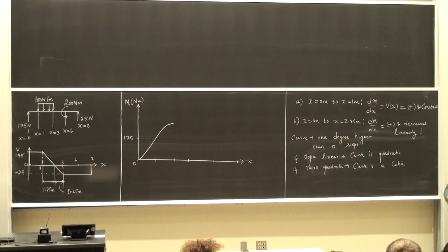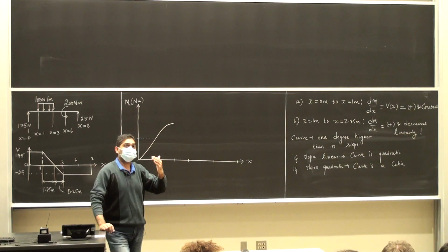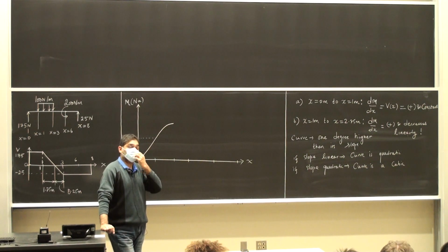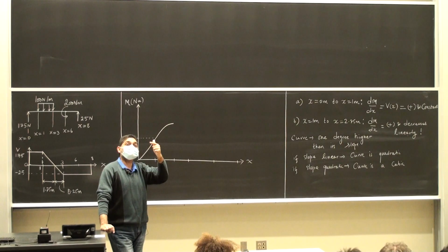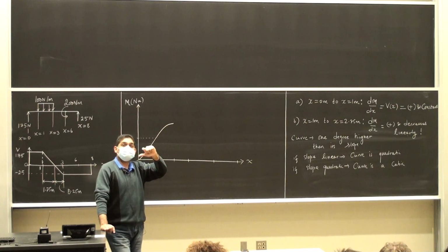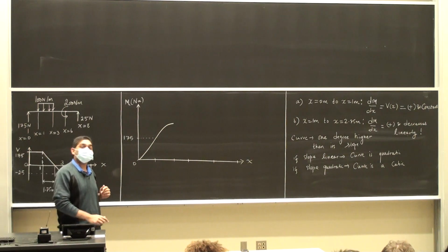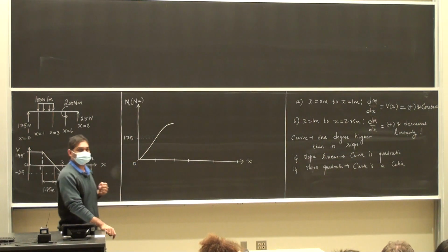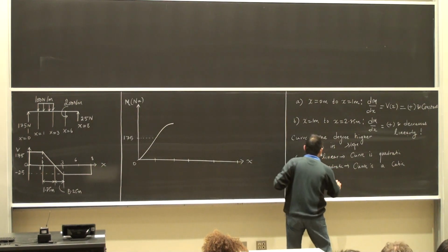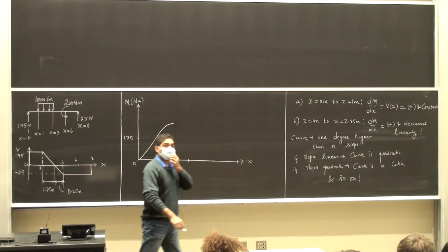It is going to be the case in the next problem that if you have a triangular distributed load, the slope of the shear force diagram is equal to the load intensity value. So the slope of the shear force diagram is going to change linearly. The shear force is going to be a quadratic. The bending moment slope is going to be a quadratic because the shear is changing quadratically. So the bending moment curve is going to end up being cubic in our next problem. Okay? And likewise, I can just keep writing this until eternity and so on. Does this make sense to everybody?